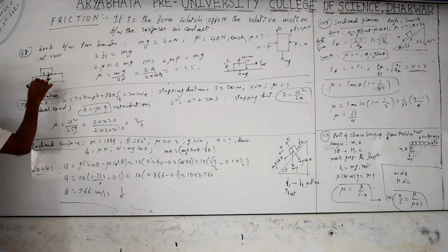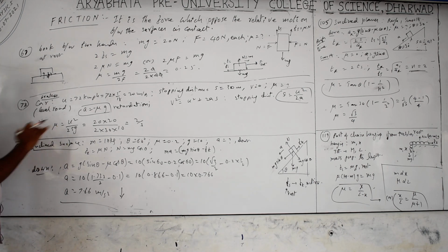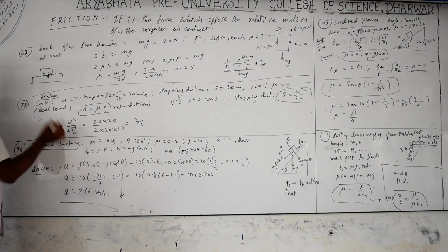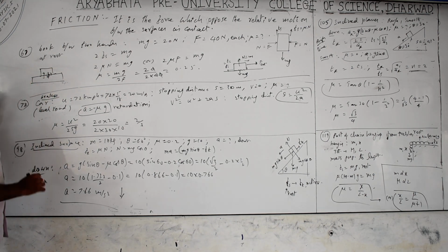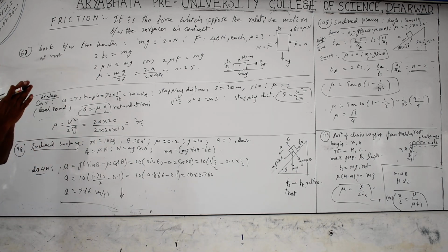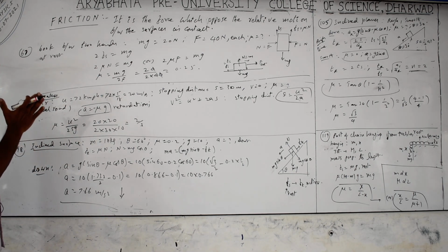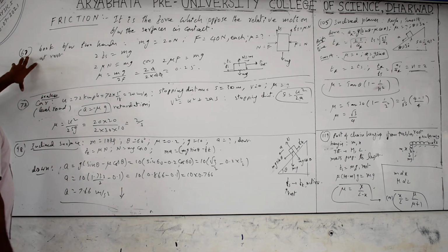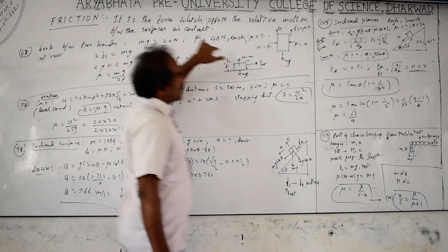Roughness is there, which means friction is more. As polishing takes place, the smoothness increases, meaning roughness first decreases and then friction increases, because of the molecular force of attraction between perfectly smooth surfaces. If you take two perfectly smooth glass plates and keep them in touch, they stick hardly because of the electrostatic force of attraction. Next we have to discuss problems, and one more thing before this, the inclined surface.